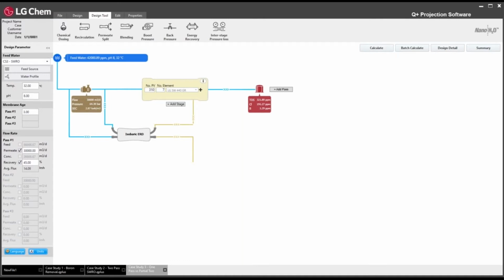So in this case, with a 30% safety margin, chloride is your most limiting factor right now because the permeate TDS is at 350, chloride's at 200, and then boron is at 2.4. So we can see here that chloride is the closest to the limit. So chloride at 200 ppm, with approximately a 30% safety margin would be about 154 ppm. So we want to target around 154 ppm.